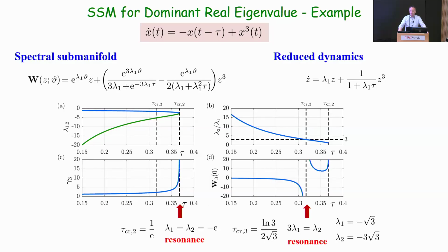But you can actually identify them, right? So I think every technique has something which we have to be careful about. And in the case of SSMs, this is the resonance. If you do control barrier functions, then you know that wherever the LgH goes to 0, that's where your problem starts to arise, right? So there is no silver bullet for everything.